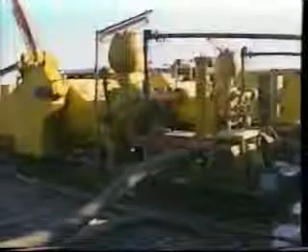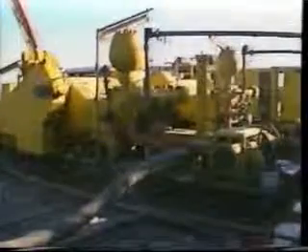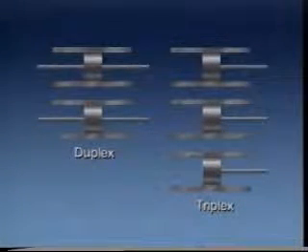Generally, at least one auxiliary pump is provided for rate and pressure control in case of malfunction during critical periods, such as a kick. Mud pumps are positive displacement pumps which utilize a cylinder and piston arrangement. This arrangement may be duplex with 2 double-acting cylinders or triplex with 3 single-acting cylinders. Triplex pumps are lighter than comparably rated duplex pumps but operate at higher speeds.